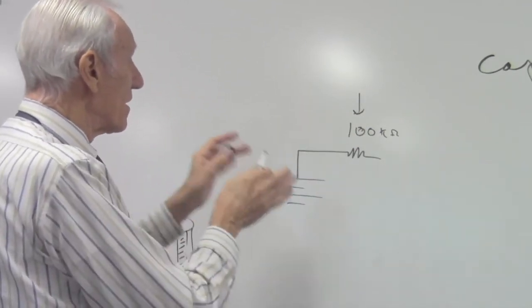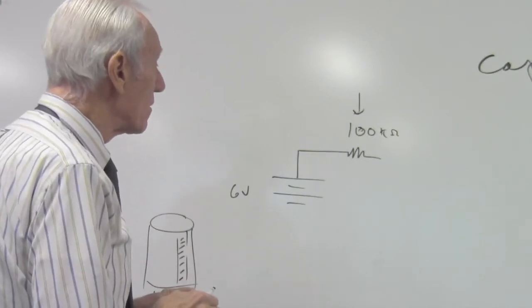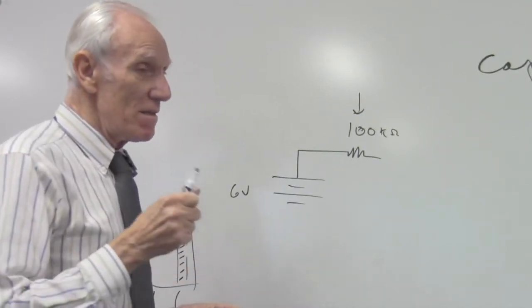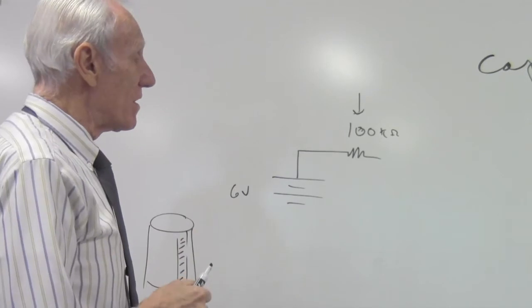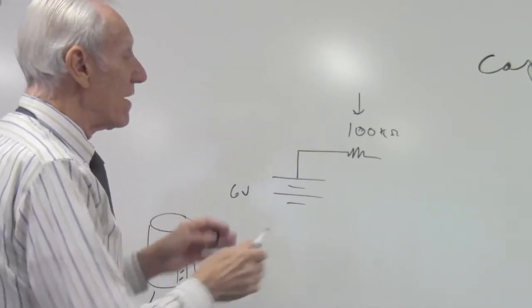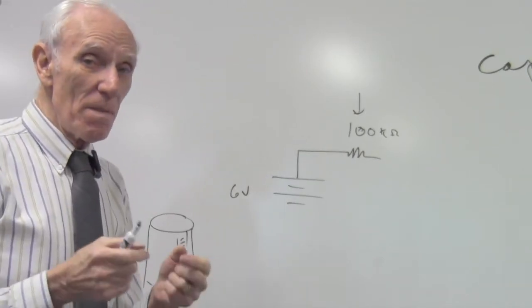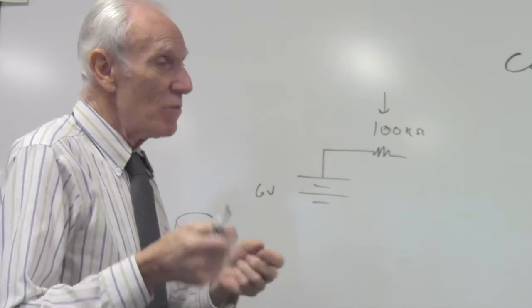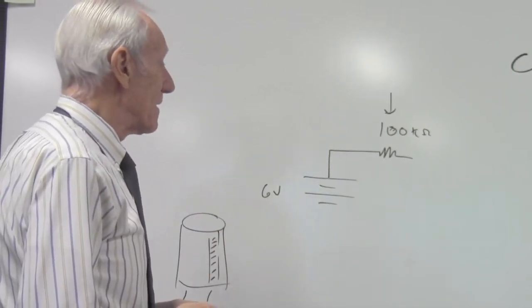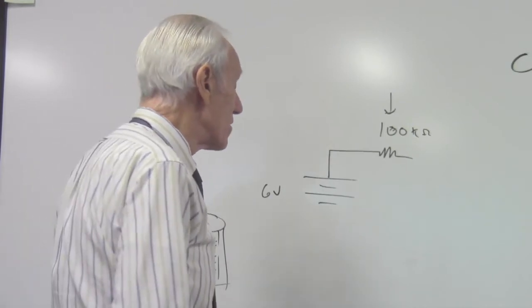So measure the resistance value very carefully with the meter, and figure out the percent error there, and that is the error in your experiment. So your values for the capacitance are going to be correct to within that small percent, probably one or a little over 1% error, depending on the resistor value.